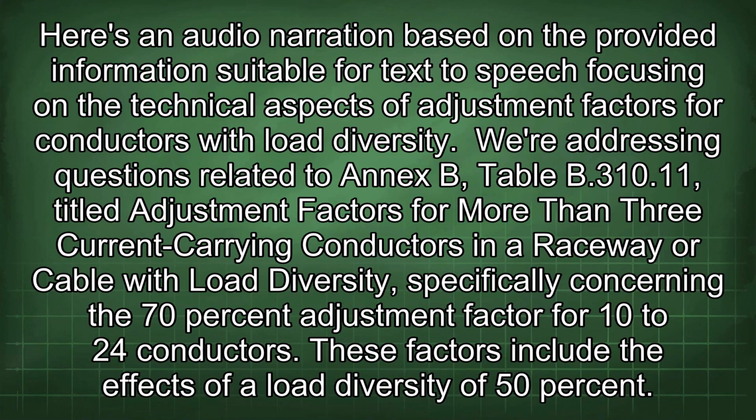Here's an audio narration based on the provided information, focusing on the technical aspects of adjustment factors for conductors with load diversity. We're addressing questions related to Annex B Table B.310.11, titled Adjustment Factors for More Than 3 Current Carrying Conductors in a Raceway or Cable with Load Diversity, specifically concerning the 70% adjustment factor for 10 to 24 conductors. These factors include the effects of a load diversity of 50%.